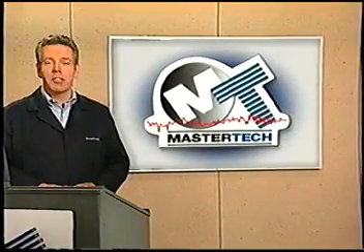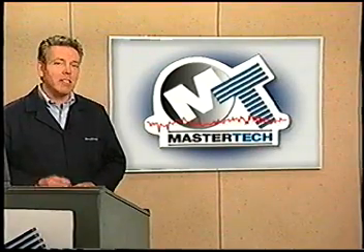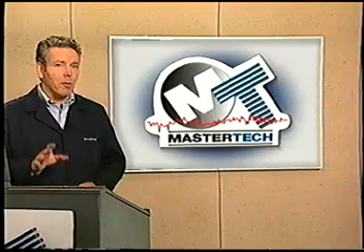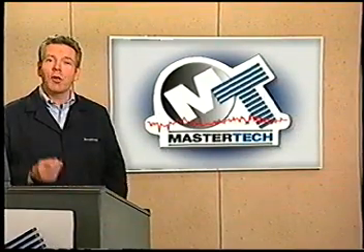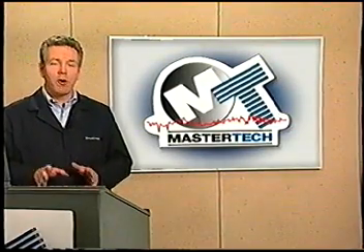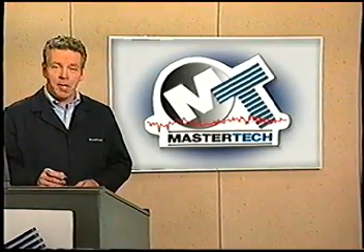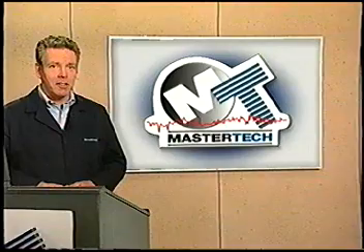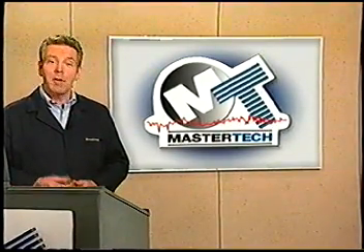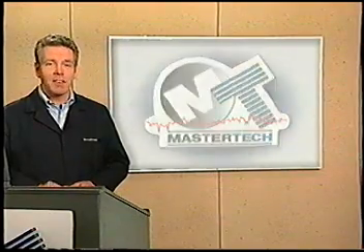At the first detection of a fault, a DTC is stored in memory and a freeze frame is recorded. However, the MIL will not be illuminated until the second consecutive occurrence of the fault. In other words, the same fault must occur in the next trip before the MIL will be illuminated. This enables the system to verify that a fault really does exist before warning the driver.